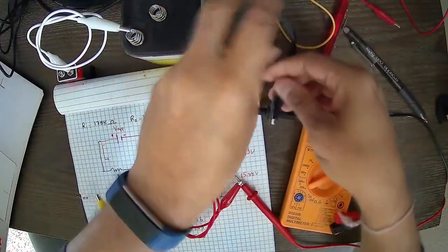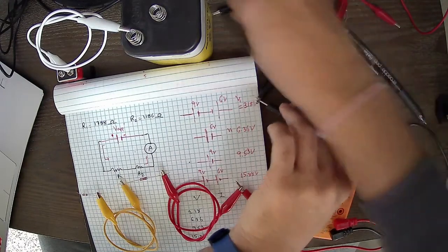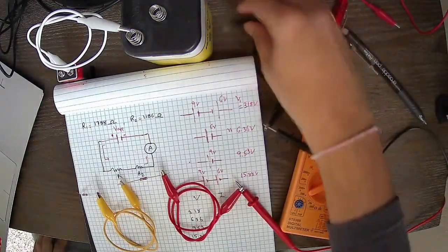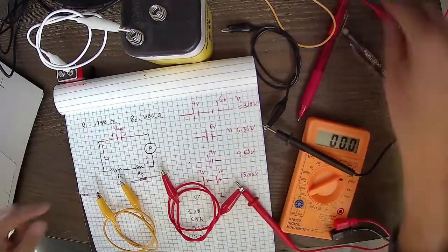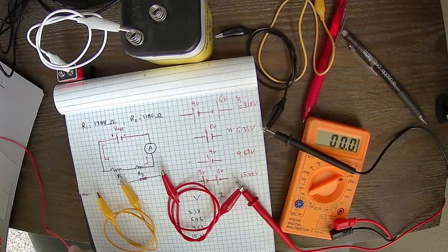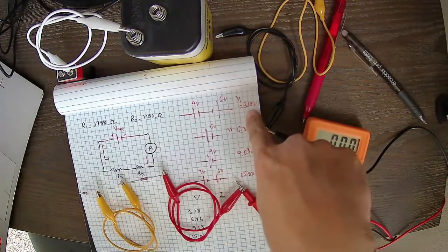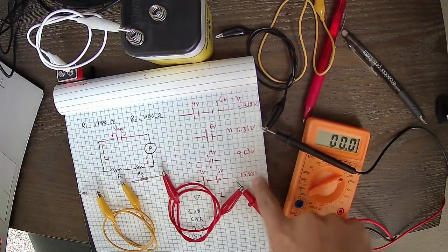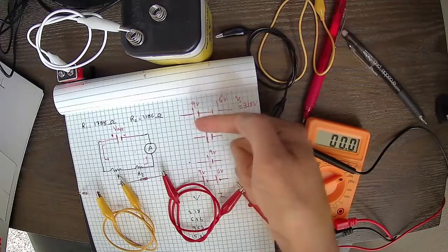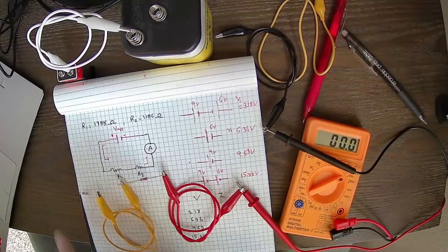Alright, so it's gonna leave from the black and hook up to the other side, correct? To the applied voltage. Now, one thing we're gonna be careful with here, when we're doing 3.18, 6.36 and all of these, is to always make sure that the positive or the higher terminal is on the left side, so that our current value always turns out to be a positive number. Okay, so we have all of this now.